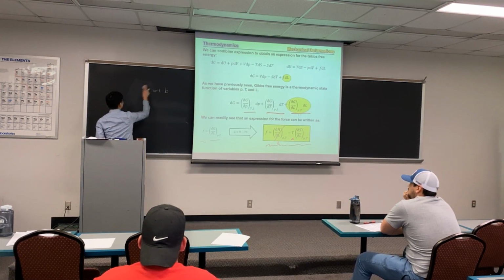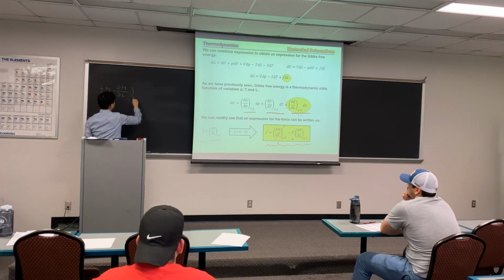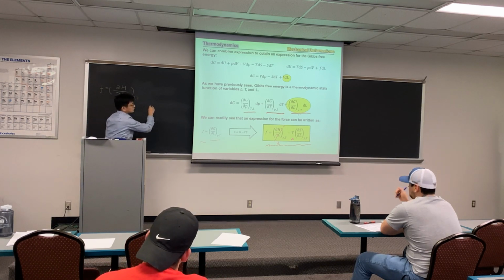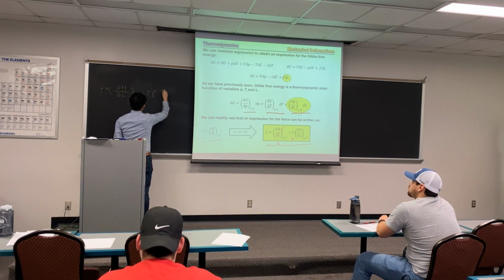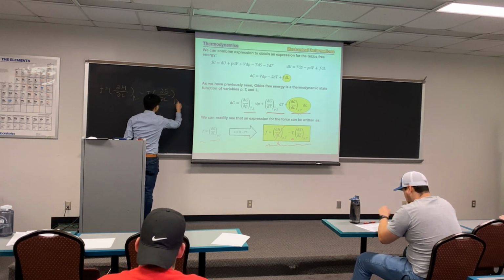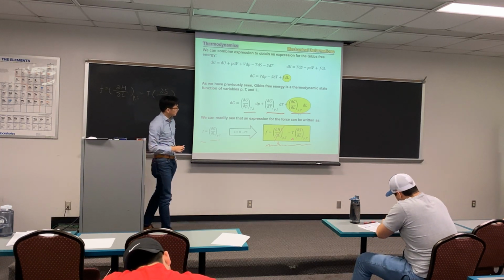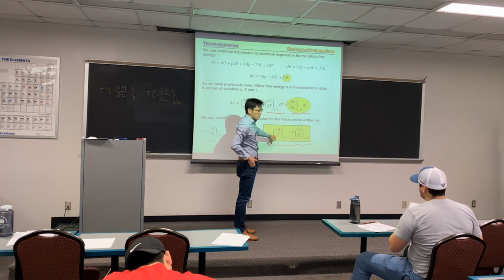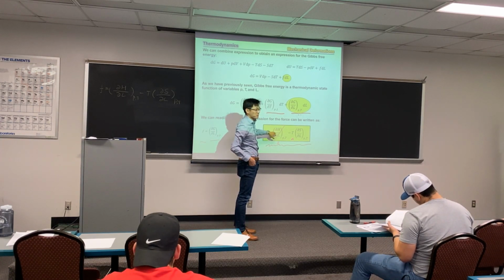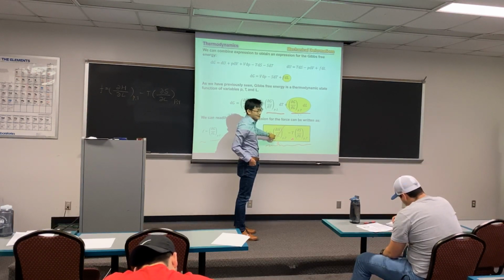How does the force link to the partial derivative of energy with respect to L at constant P, T, minus T times the partial derivative of entropy S with respect to L. We will discuss in a moment how to understand these partial derivatives with respect to L, or displacement.